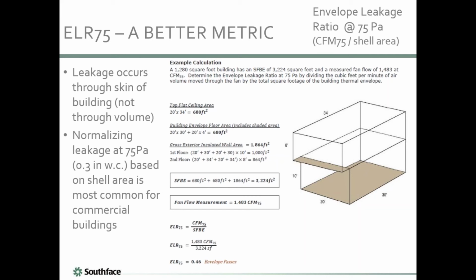The other thing we want to talk about is this concept of what do you do with that number. So in homes, many people, if you've done blower door testing, are familiar with this term called air changes per hour at 50 pascals, ACH 50. It's our industry standard reference point. It's used in code, and it's used in beyond code programs as well. And why are we not crazy about that term, the ACH 50? Why air changes per hour? Well, not our favorite term.